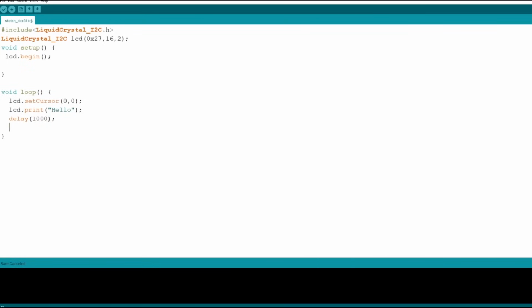If you want to use the clear function, firstly we will call our LCD variable name. So my LCD variable name is lcd, and then put a dot, and let's write here clear and open and close parentheses and put a semicolon. If you do something like this, we will clean our LCD screen. So let's continue. So now let's move to a new line and call our print function again, because we will print CU. That's why we call the print function again.